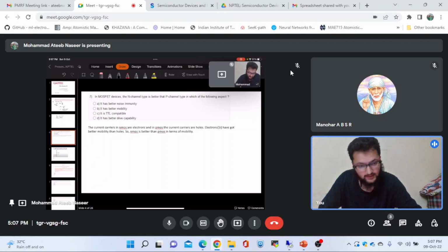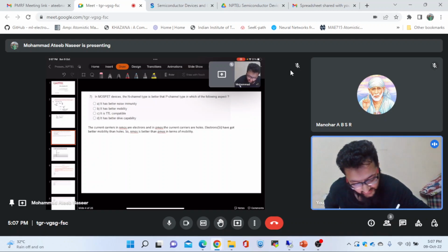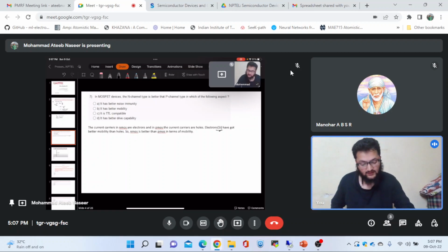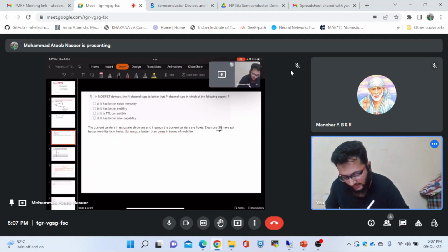It says that the current in the NMOS is carried wholly by the electrons, and in the PMOS the current is carried by the holes. Electrons in silicon have got higher mobility than holes. So NMOS is better than PMOS in terms of mobility. So we will go with option B.